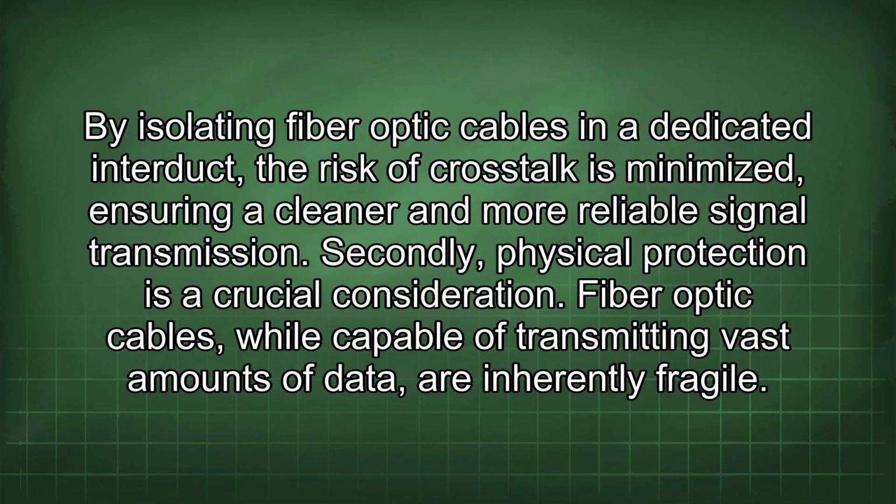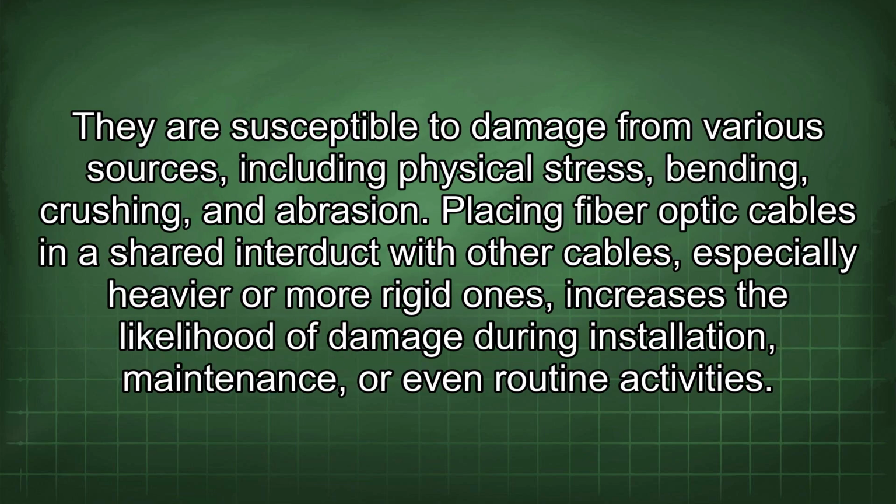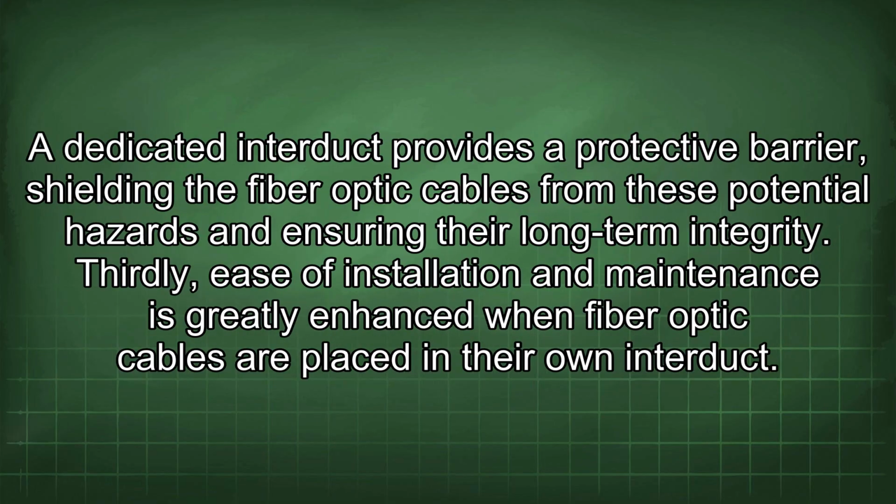Fiber optic cables, while capable of transmitting vast amounts of data, are inherently fragile. They are susceptible to damage from various sources, including physical stress, bending, crushing, and abrasion. Placing fiber optic cables in a shared interduct with other cables, especially heavier or more rigid ones, increases the likelihood of damage during installation, maintenance, or even routine activities. A dedicated interduct provides a protective barrier, shielding the fiber optic cables from these potential hazards and ensuring their long-term integrity.